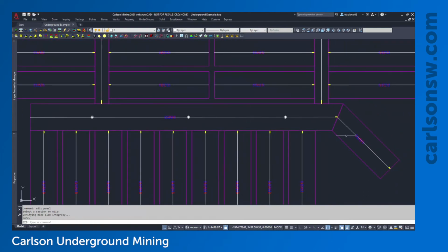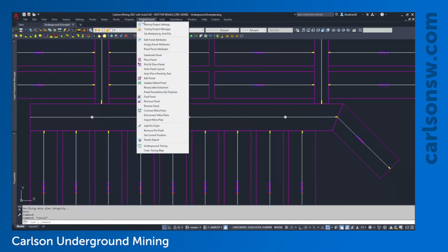So let's suppose that I have a continuous miner working on this main panel, and I have a second unit that's going to work on these production panels. Obviously, I can't start mining the production panel until my main panel has mined at least up to this point. So what I'm going to do is add a precedence rule that prevents this panel from starting until I've gotten at least up to this location. Now, there are a couple ways that I can define precedence rules. The first one is fairly slow, but very easy to work with.